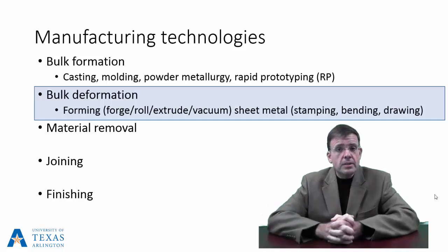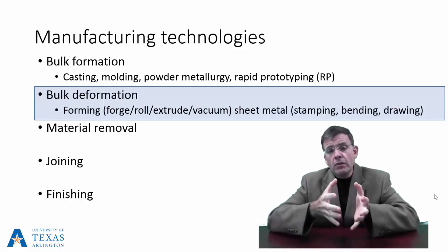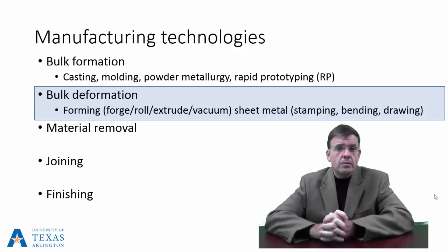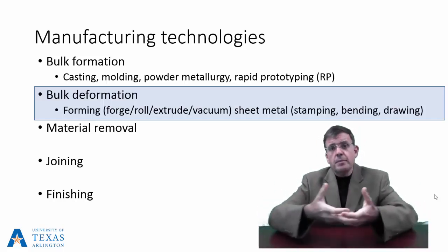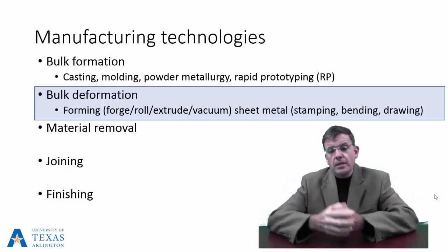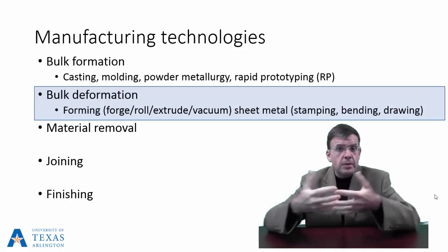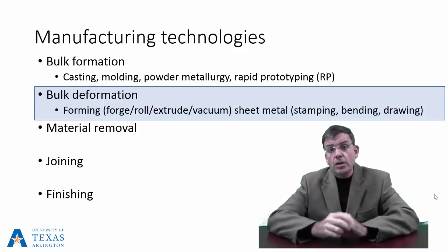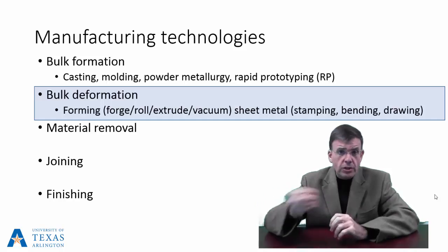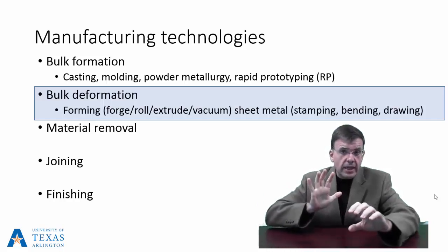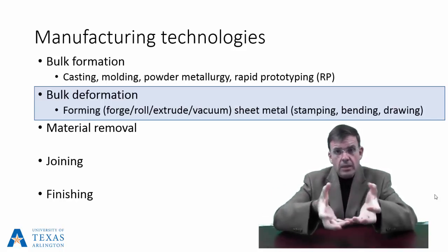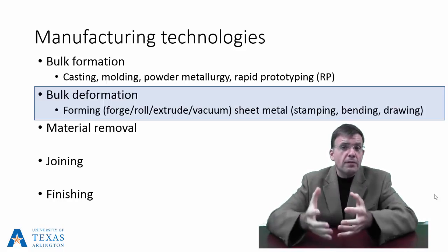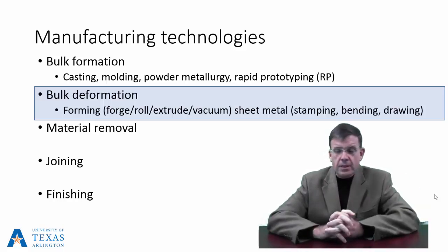Okay, rolling processes. This type of process is made oftentimes to create the stock material that we purchase. So we talked about commercial off-the-shelf metals, for example, commercial off-the-shelf plastics. They come in bars, they come in sheets, ingots, in beams, in angles, in U-shape channels, etc. So these are the processes that will create these stock material shapes. Okay, extrusion is also a forming process. In that case, we are actually shoving the material through a die to give it a constant cross section. So that has a direct parallel to our beloved extrusion in SolidWorks, parametric solid modeling.